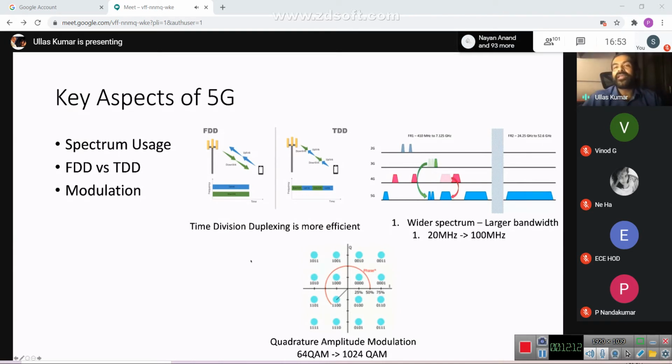So you can easily think, why limit at 1024? Why not 2048 or higher? Some of you might have already seen this guy called Shannon. He established a theory called Shannon's limit of channel capacity, which says that you can't infinitely increase the channel capacity by increasing the power. At some point, you will have to deal with the noise. And we are trying to understand what that noise is and how we can reduce it. That's why at every stage of the wireless network, we are trying to reduce the noise and increase the capacity to process. There's also a lot of processing that is done, and now it is possible with the latest digital signal processing and chip technologies to process at that level.